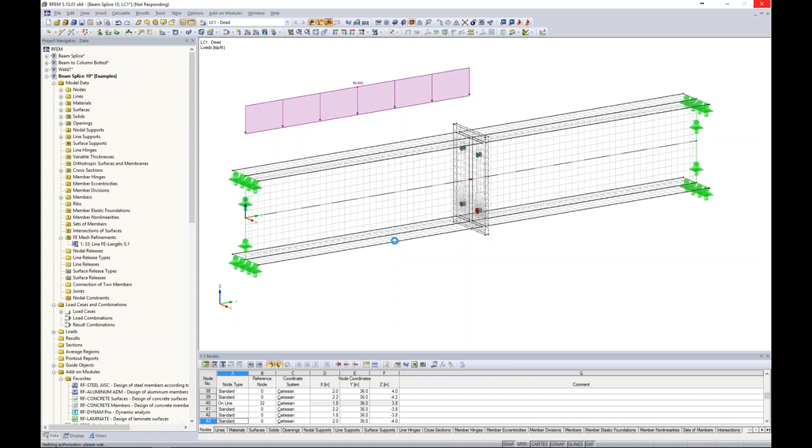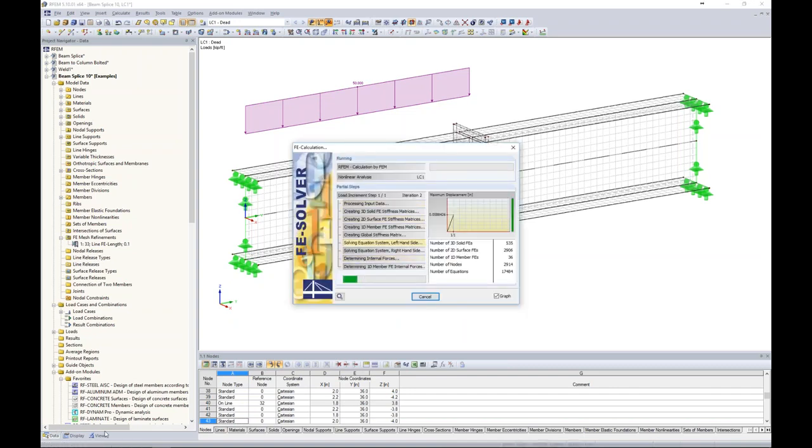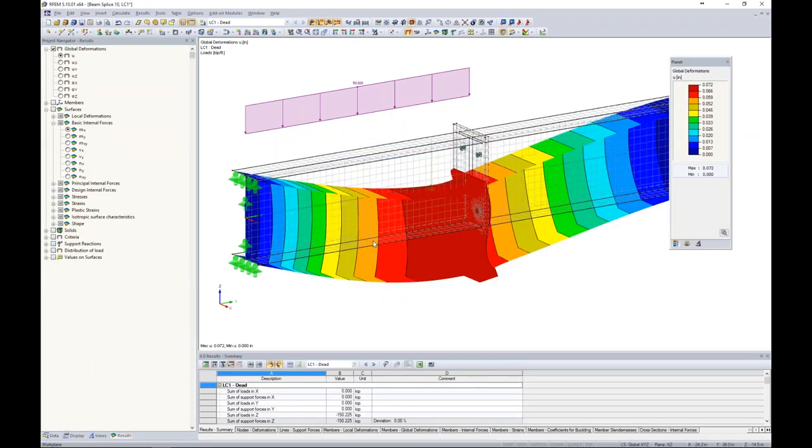And keep in mind too, we can see down here what the program's doing. It said verifying authorization, so it was checking my license. It is a nonlinear analysis program, so the contact solid is something that's going to increase our solution time as well, and that's just because of that different behavior that we defined between the two plates. So that analysis is run, and we are automatically brought into our results tab here, which is available within our project navigator that I mentioned at the beginning of the webinar.